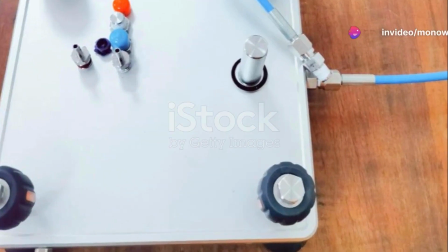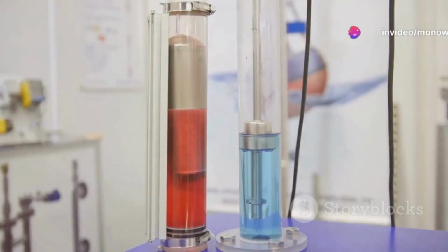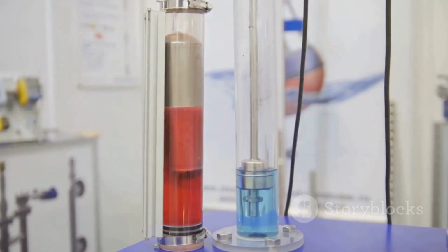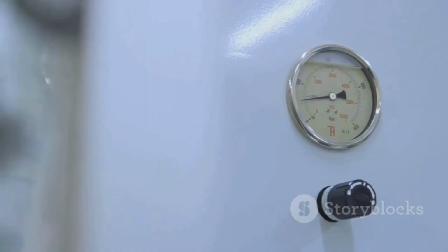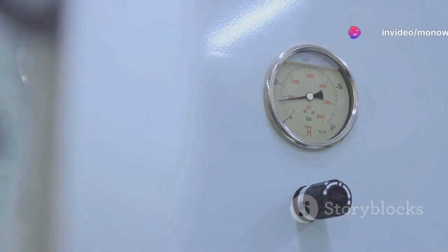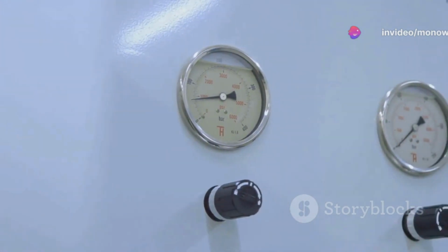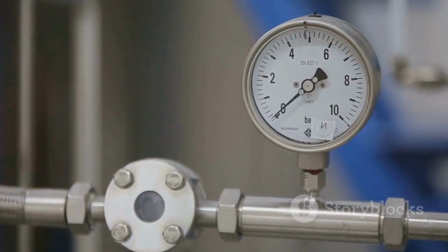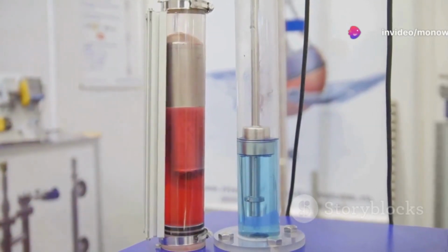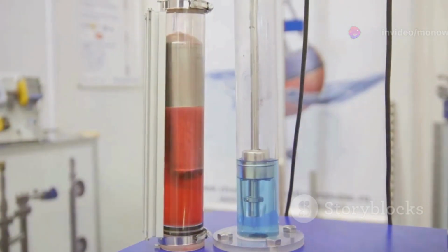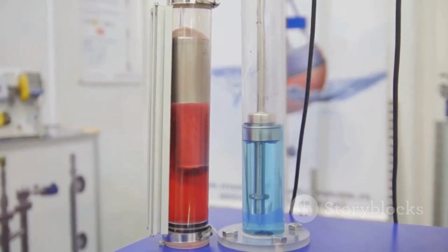Next, the guidelines help technicians prepare the device for calibration. This could involve cleaning, zeroing, or adjusting the device to ensure it's ready for the process. Then comes the actual calibration process. Here, the device is subjected to a series of tests, comparing its readings to those of the reference standard. Any deviations are noted and adjustments are made to align the device's readings with the reference standard. After the adjustments, the device is retested to verify the accuracy of the calibration. This process is repeated until the device's readings match the reference standard within an acceptable range.